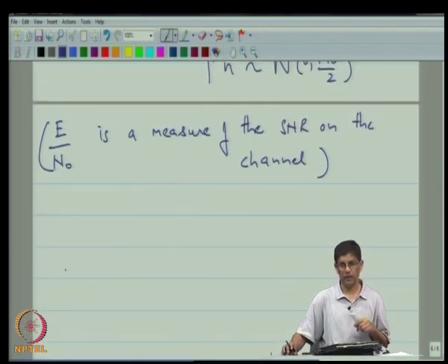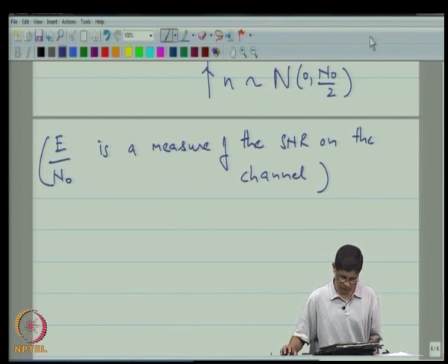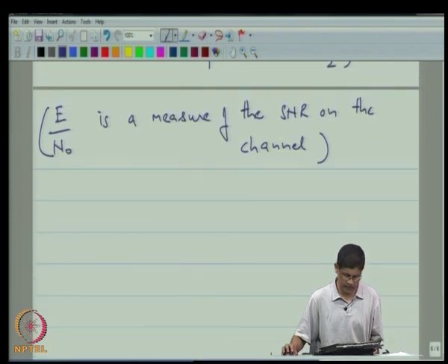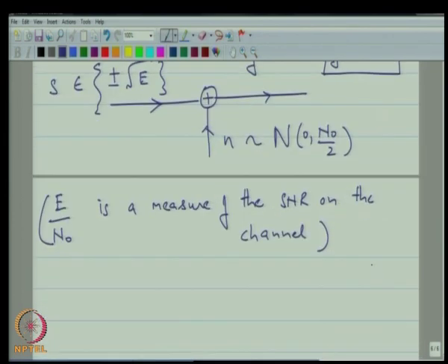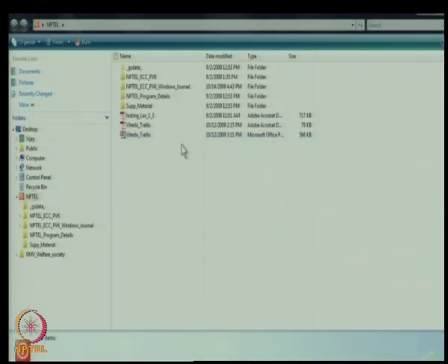And some time back when we discussed maximum likelihood decoding over the binary symmetric channel, we showed that the minimum probability of error decoder ended up as being minimum Hamming distance decoding. So, there is an analogous result here. Okay, so let me see if I can quickly pull that up from our earlier lectures.